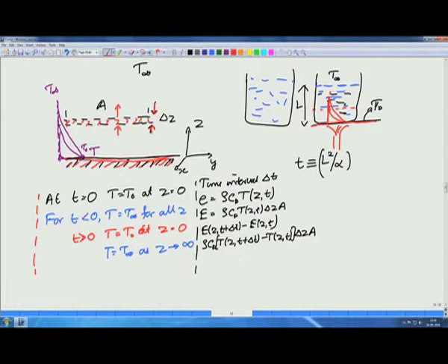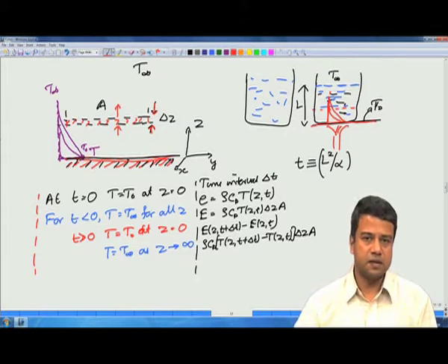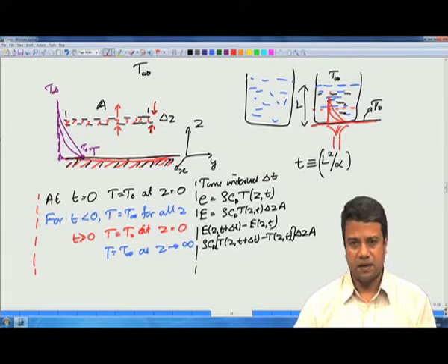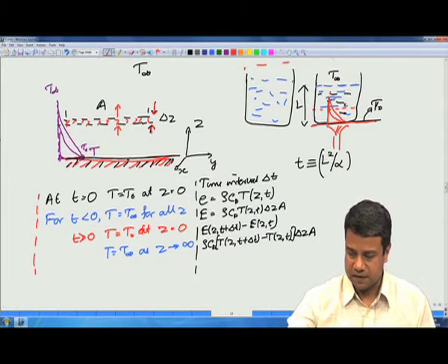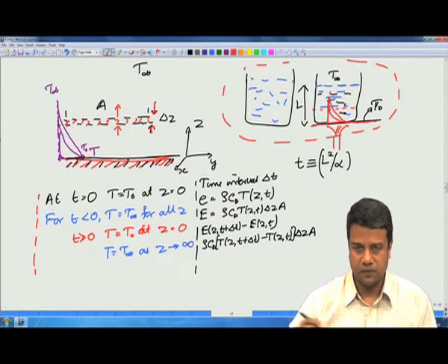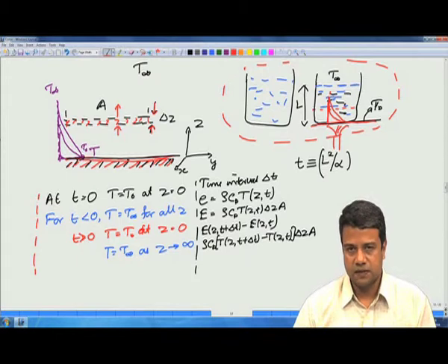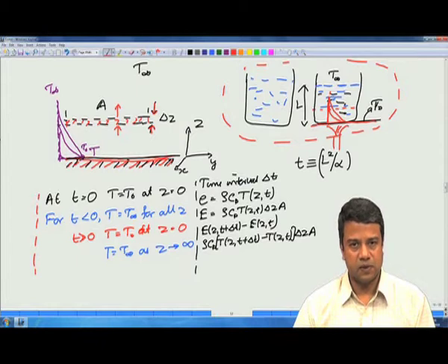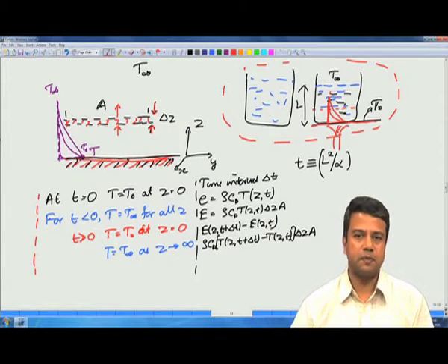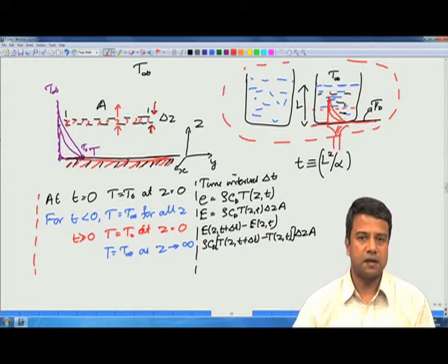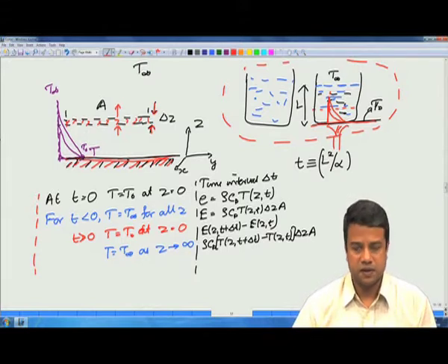In the case of heat transfer, it corresponds to having an infinite surface in which initially the temperature everywhere is a constant, and at initial time we instantaneously increase the temperature to a higher value. It corresponds to something like heating a surface, a container of liquid. We make the assumption of infinite fluid, and that approximation is valid only when the penetration depth of the temperature field due to this heating into the fluid is small compared to the system size.